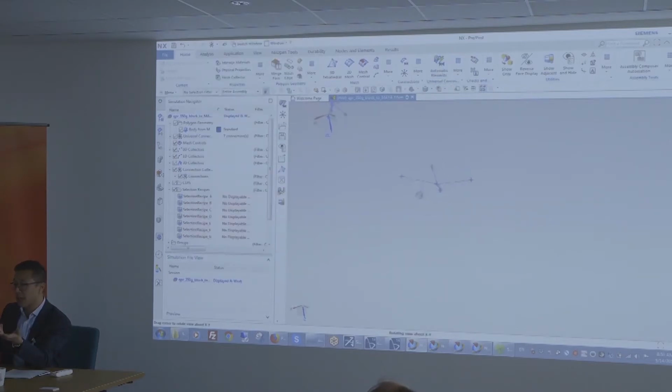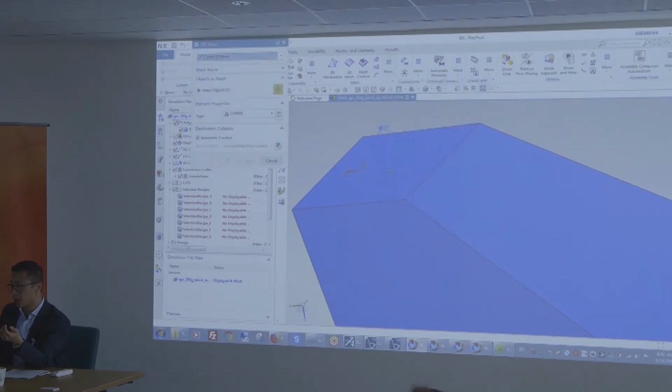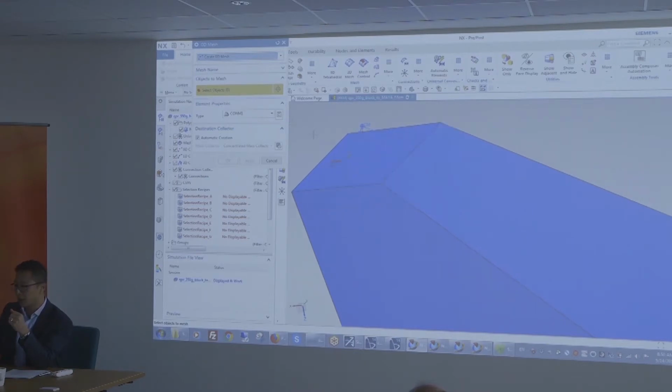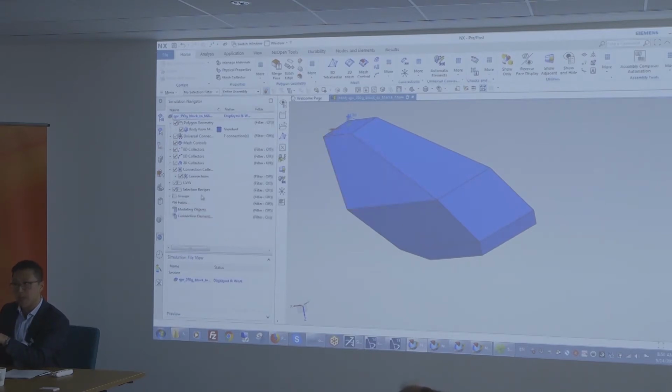And obviously I need something a bit more complex. So what I've added is a simple lump mass here at the top, which I can create using our 0D mesh capabilities, a mass of, in this case I think, 350 grams. So this is the first part, the mesh that I've created. I've only meshed it and created some connections. And from a topology optimization standpoint, that's all I need to define in terms of meshes from a structural perspective.